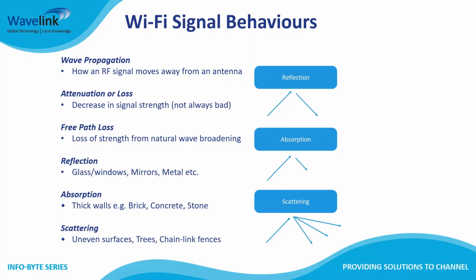Your reflection, so again, reflective surfaces themselves, so glass, metal, anything with a reflective surface, the signal itself can reflect off and go in weird ways. Absorption, fairly standard, thick brick walls, reinforced concrete, double brick, Besser brick, trees. Good Lord, do trees love to kill Wi-Fi? They love to absorb and scatter because of the trees and the branches and the leaves, all that sort of stuff. So again, scattering there as well. But then we also have diffraction and loss and other bits and pieces as well.